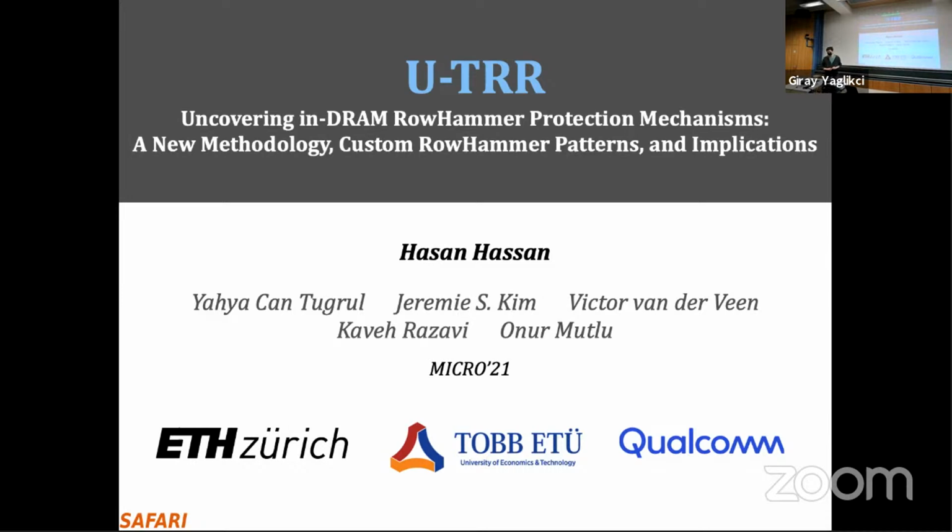I don't think so, or not yet. But this is not the first work to show that the TRR mechanisms are not effective. The TRRespass paper showed that before. That was known at the time you published this paper, that these TRR mechanisms are not completely secure, but we showed exactly why and how you can bypass those TRR mechanisms in a more efficient and more effective way.